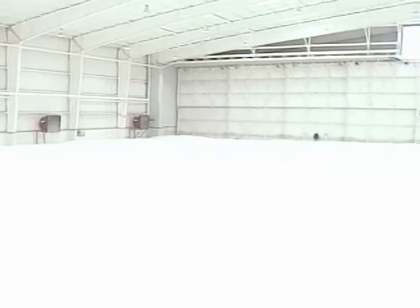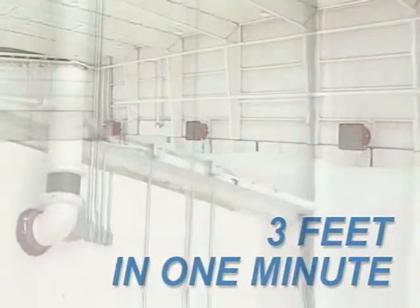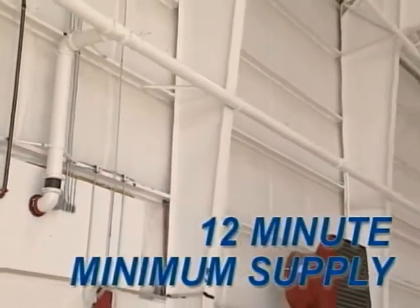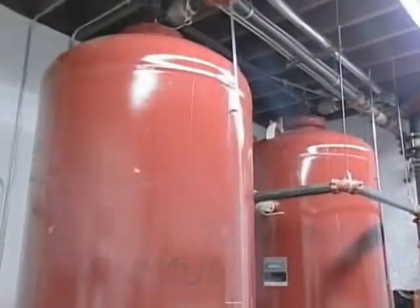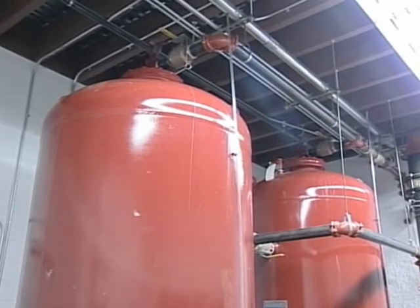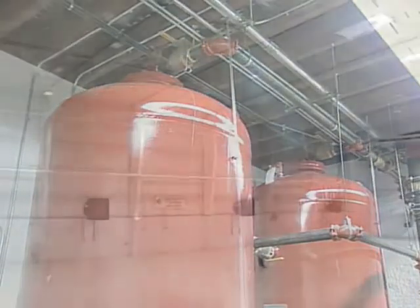According to NFPA 409, the supplementary high-expansion foam system has to fill the aircraft's storage and maintenance floor area to a level of 3 feet within 1 minute. The system also required a sufficient supply of foam solution to continuously operate the system for 12 minutes. A directly connected reserve supply of foam equal to the main supply is also required in NFPA 409.